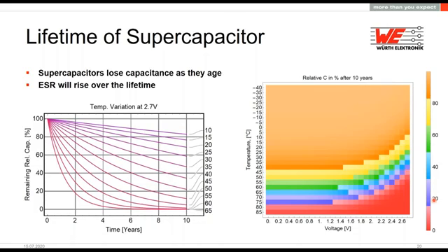But please keep in mind that you need some infrastructure so that you can use it until 0 volt. So you need a really good step-up or SEPIC converter, which operates to a really low cutoff voltage. When there are, for example, 0.5 or 0.2 volt ICs, then you can use it nearly to 0 volt, but there will be some voltage left in the supercapacitor because you cannot use it until completely 0 volt. But of course they will discharge themselves and then they are 0 volt.